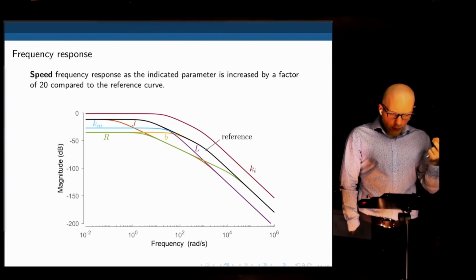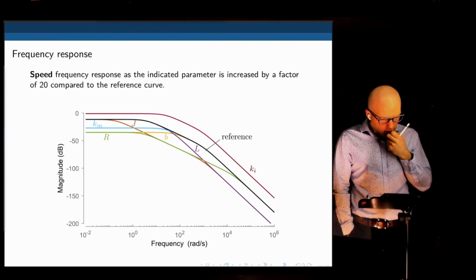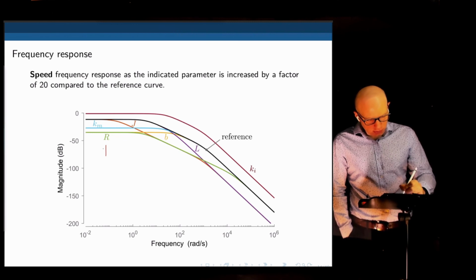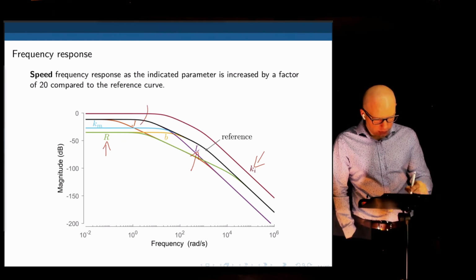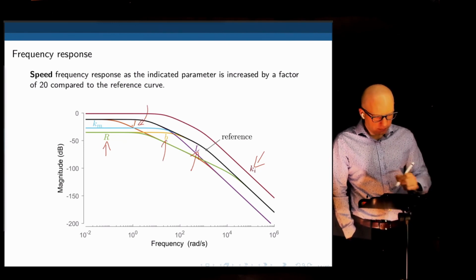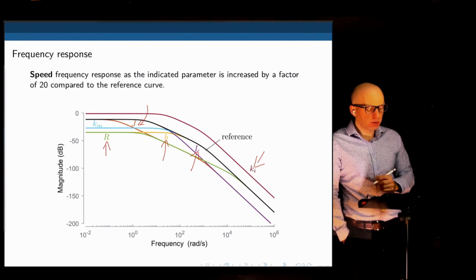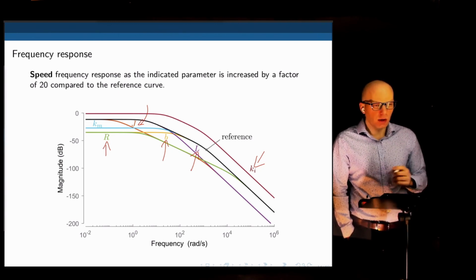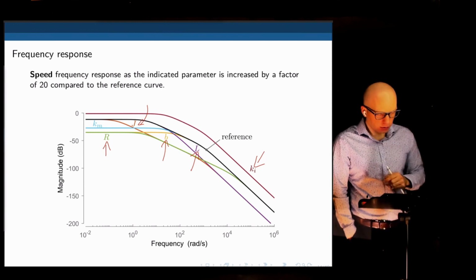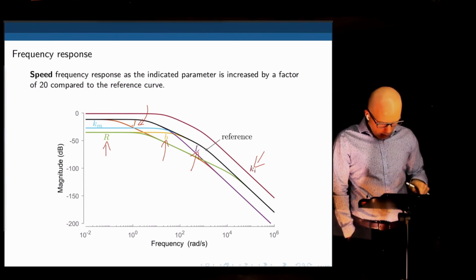This is to say that if you want a good motor, what should we see in a good motor? We should see low values for R, low values for L, high values for Ki, low values for J, low values for B. We should try to maximize Ki. Okay, unfortunately, Ki and Km are connected, so that's not really an option.